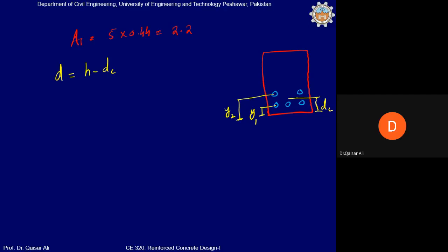अच्छा, इतना तो आप बता सकते हैं, this centroidal point, it will be closer to layer 2 or layer 1? Layer 1. Layer 1, because reinforcement in layer 1 is greater than reinforcement provided in layer 2. Clear? अच्छा, ये किस तरह से कैलकुलेट करेंगे? ये बिल्कुल सिंपल है. The dc will be equal to A1 y1 plus A2 y2 divided by A1 plus A2.